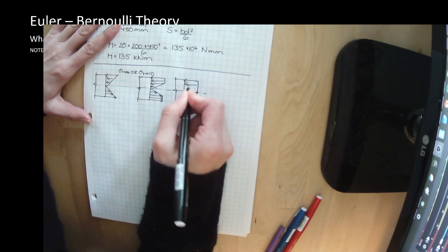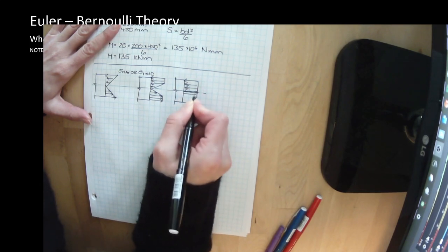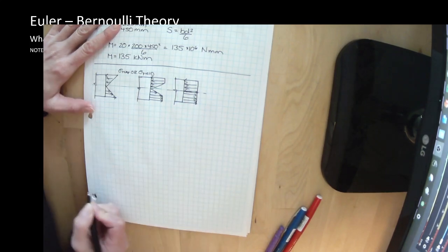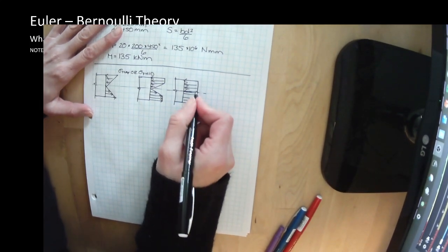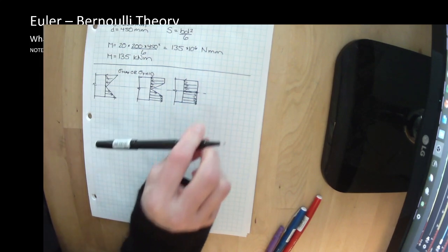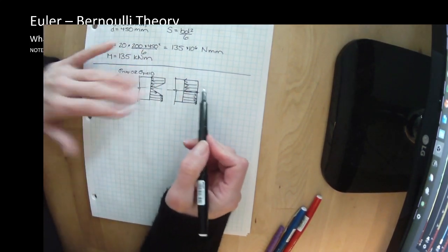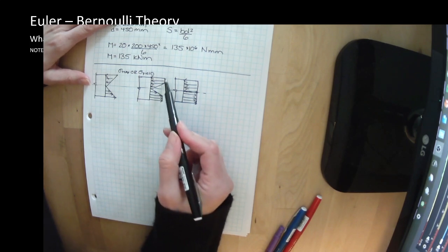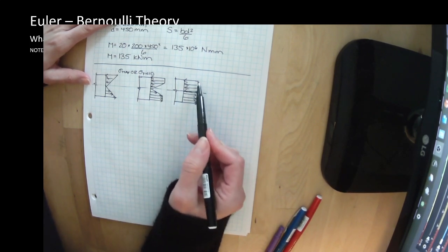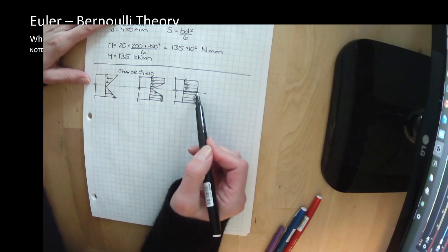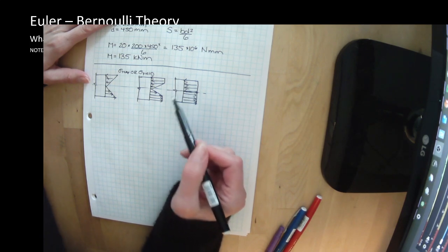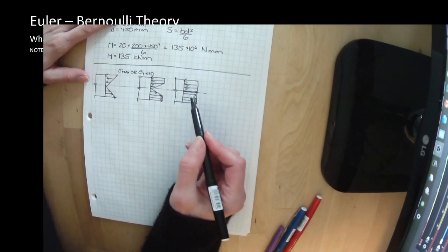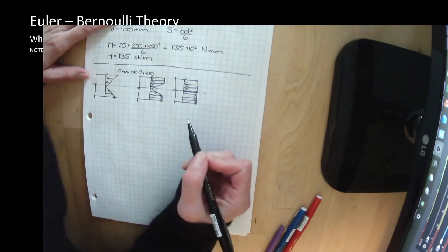So that all of this side is hitting the maximum and all in compression, and all of this side is hitting it in tension. So we're not yielding it all the way through, we're yielding it just to the neutral axes. We're almost getting to the point where we're going to have some permanent deformation when we unload it at the top and bottom of this member. And here we're going to have some permanent deformation all the way down to just shy of the neutral axes. After this, we're going to see large-scale deformations through the whole thing. You almost can think of it as a runaway cart at that point. But right here, we are just shy of it happening.